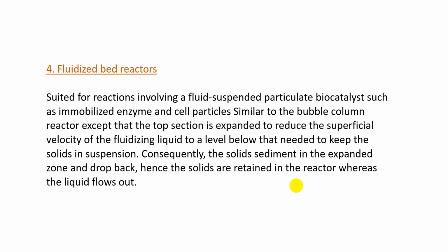So it is suited for reactions involving a fluid suspended particulate biocatalyst, such as immobilized enzymes and cell particles. This is similar to the bubble column reactor, except that the top section is expanded to reduce the superficial velocity of the fluidizing liquid to a level below that needed to keep the solids in suspension.